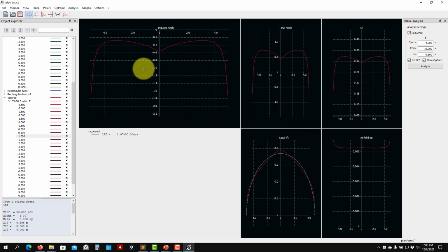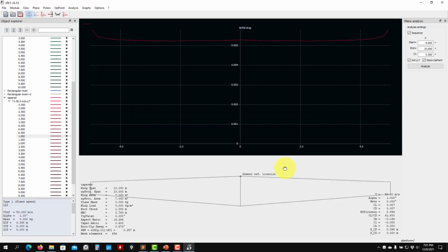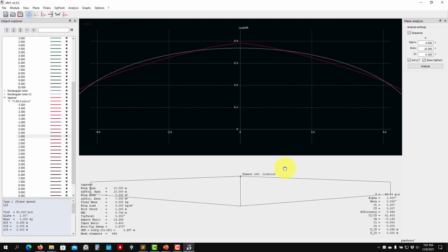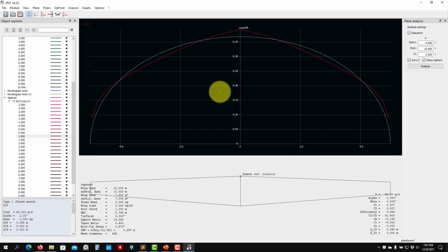The only thing that we have here now, if you look at the CL, is that maybe the stall is very close to the tips of the wing, so probably we can add a small twist and shift this inboard to avoid that problem. But if I go here, 4, 5, 4, perfect. See that this is very close. This is already a very good solution. We can, okay, improve it a little bit.